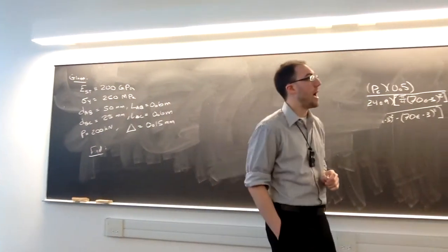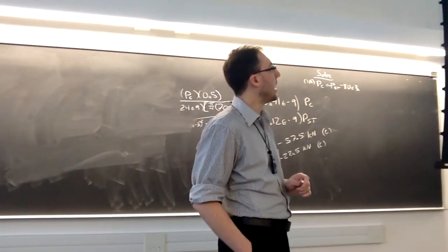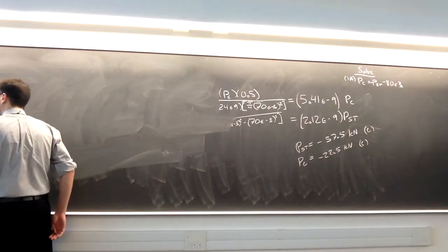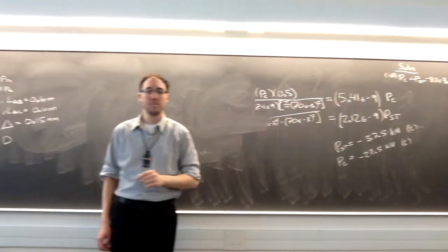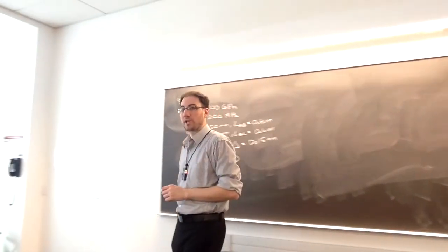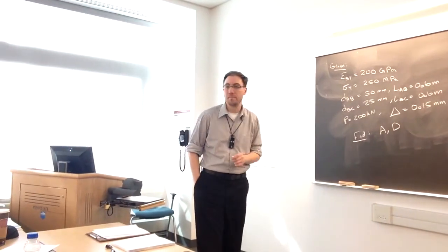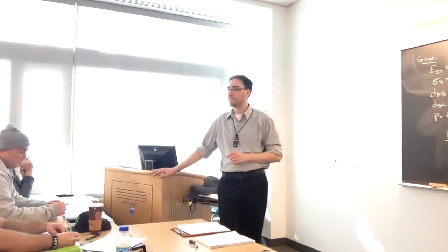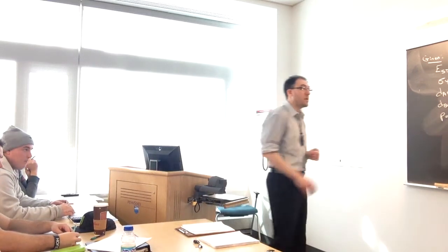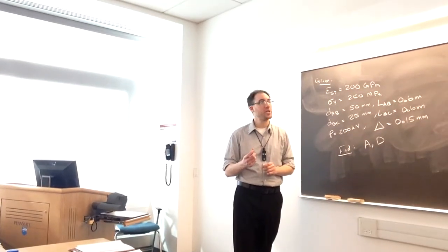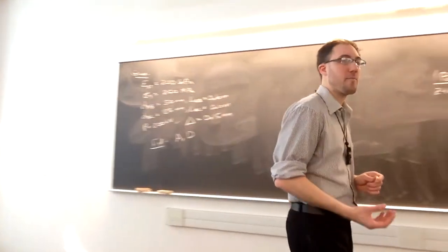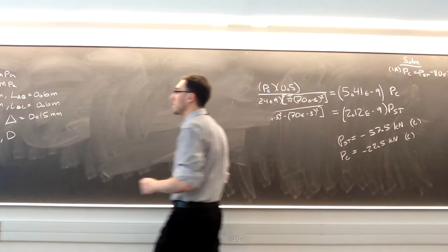And we want to find here, after it's loaded, what's the wall reaction at A and what's the wall reaction at D. All right, questions so far on what we're looking at here? We have all one material, but the cross-sectional area changes between AB and BC. Also, the internal force changes between AB and BC. For our free body diagrams, then, we're going to need how many sections to solve this one?